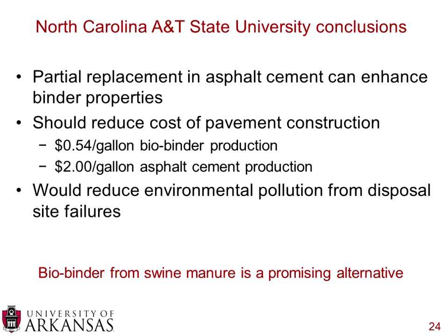But if you're looking at a material replacement cost comparison, this does reduce the cost of pavement construction. Biobinders are about a quarter of the cost of asphalt cement, and that includes all of the production. So a tank of biobinder coming out of the production facility is a quarter of the cost, 50 cents, compared to $2 a gallon of asphalt cement coming out of a refinery.